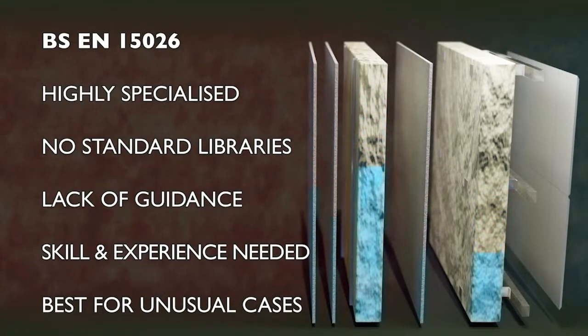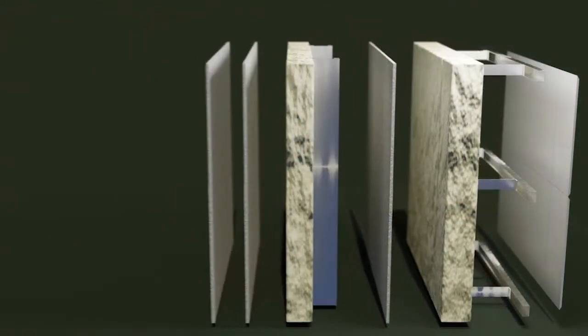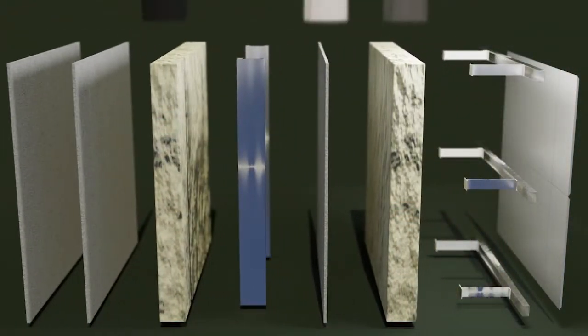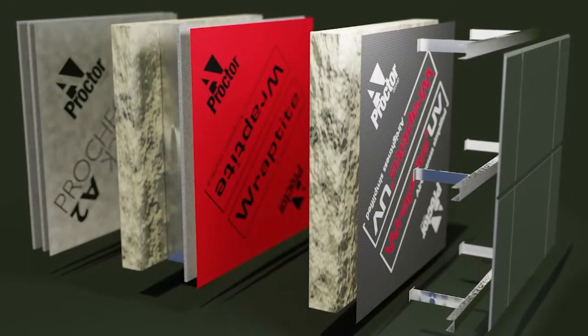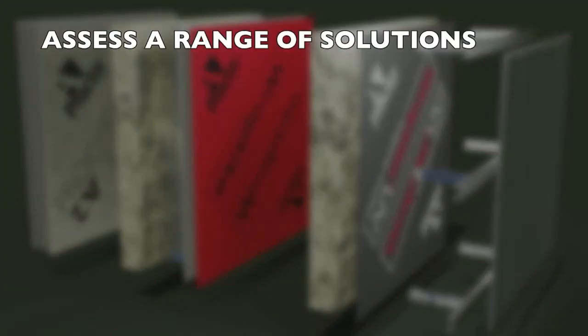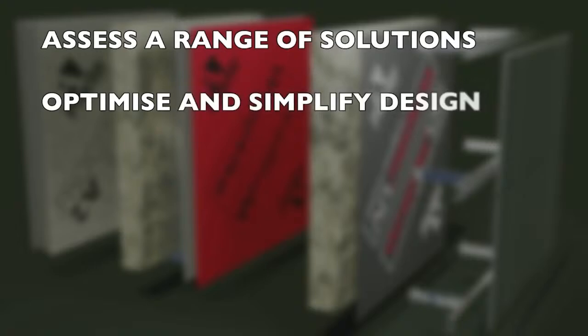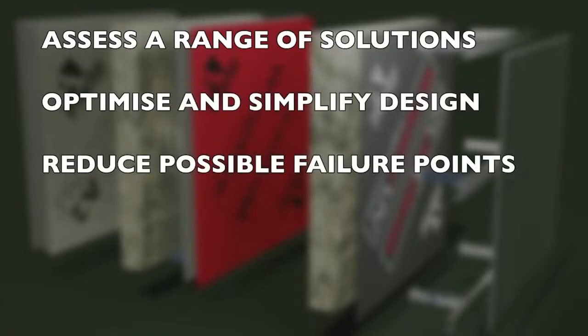highly optimised cases. The results of these condensation risk assessments can be used to assess and confirm the effect of different combinations of insulation and membrane permeability. This allows the hygrothermal performance of the facade to be optimised to ensure a robust, durable and economic solution is achieved. In this way, it is possible to assess solutions such as removing the internal AVCL in favour of an external air barrier, which removes a potential source of complexity and reduces potential failure points in the design.